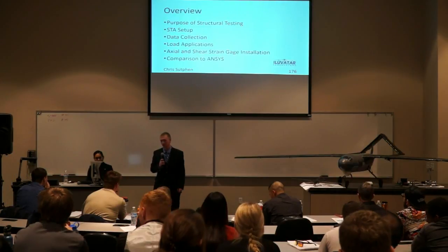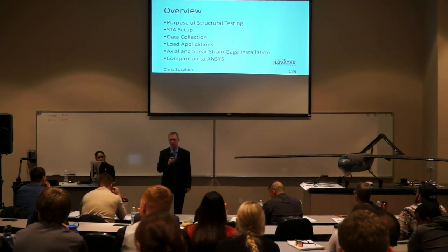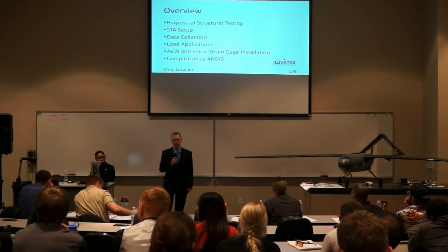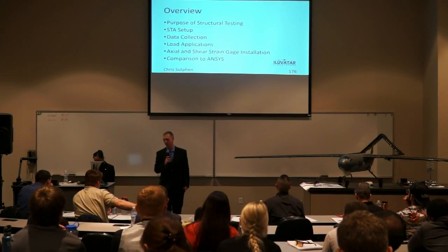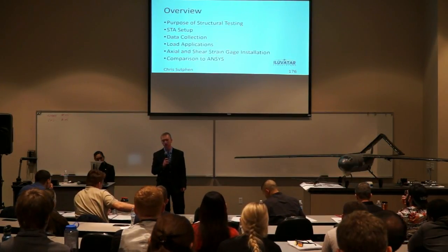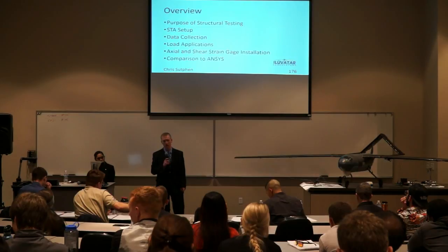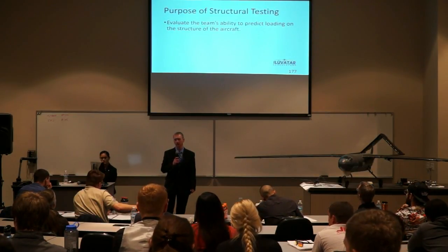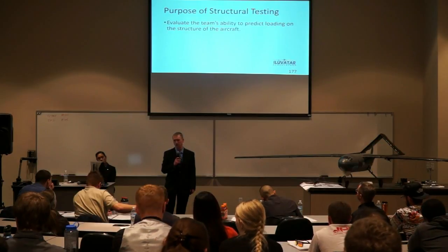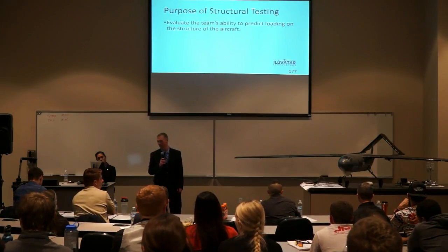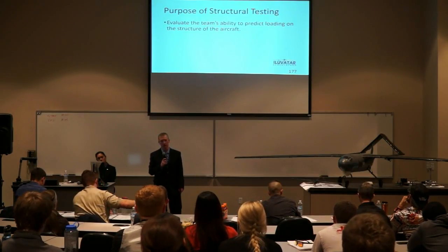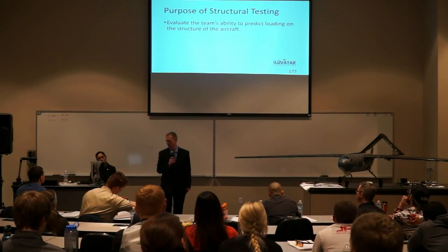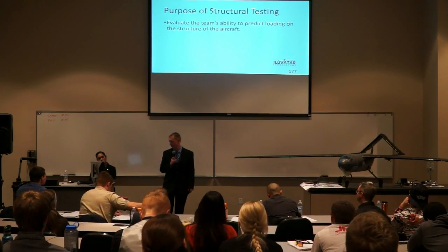So I'll be going over the purpose of structural testing, our STA setup for testing, our data collection, our load applications, our axial and shear strain gauge installation, and our comparison to our ANSYS results. The purpose of this was basically to collect data to compare to our ANSYS results. The main thing we were looking for was deflection because we were worried about the wing being overly flexible, which is what we found out it actually was.